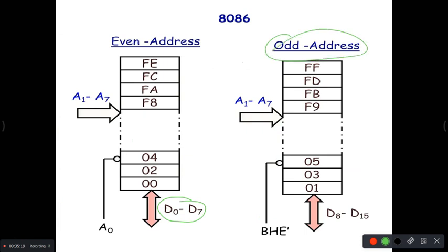Whenever you design an IO interfacing, if you want to read 16-bit data, the data transfer has to be arranged so that the device has two port addresses and gives 16-bit data from the two addresses.